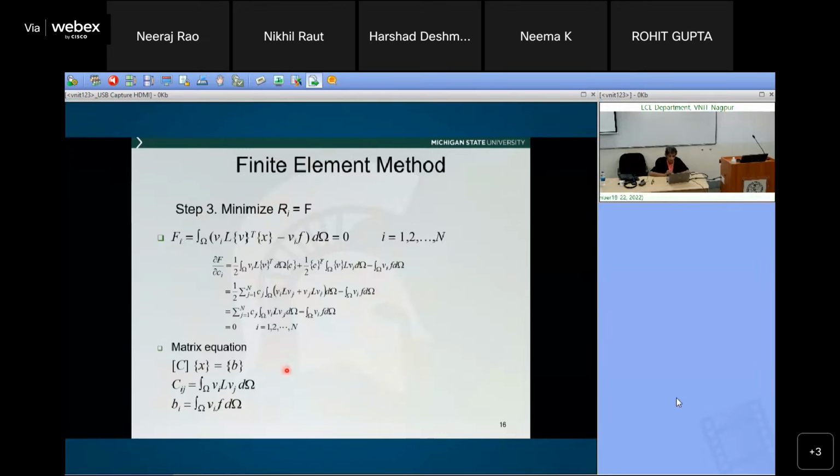In the case of static and quasi-static, like eddy current, it's a very local phenomenon. Even if you have 1 meter, I'm just going to model around the defect. That's all I'm going to model. Look at the signal. If you have wave propagation, it's a different ball game, really. Those are different problems, and maybe an analytical or semi-analytical method is not what needs to be used. If you're trying to model an ultrasonic wave, ultrasonic inspection or a microwave inspection, it will be a slightly different problem.